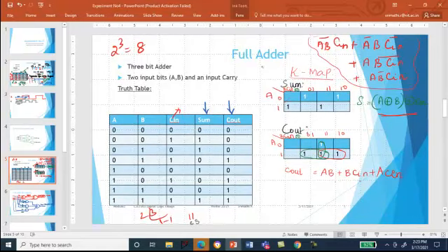Step 2 is nothing but we need to go for the K-map, because we need to realize this full adder circuit in LTspice. So how many inputs? You have 3 inputs. So in the K-map, it's a 3-variable K-map with 8 possible cells, possible input combination cells. So A will take 2 values, 0 and 1, and B and C can take 0 0, 0 1, 1 1 and 1 0. So now what is it that we need to do? We need to fill this table up.